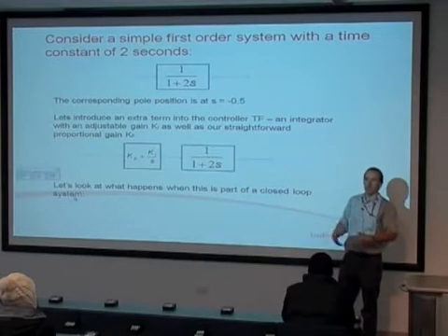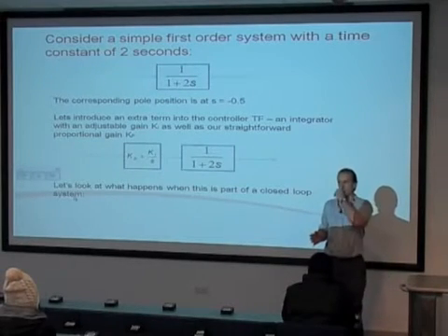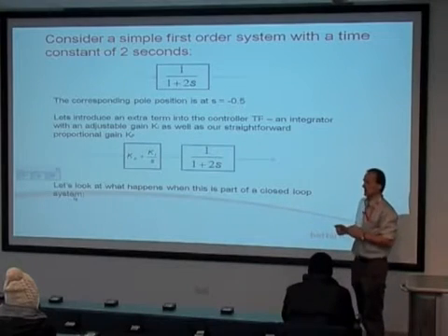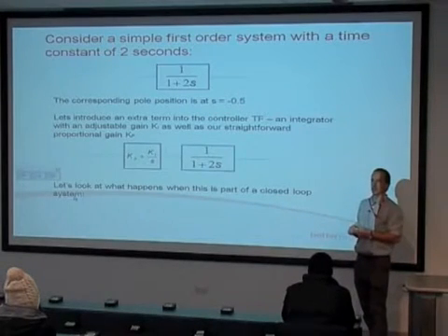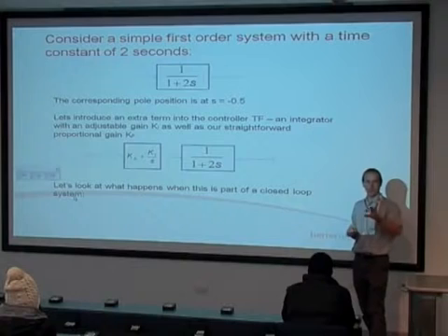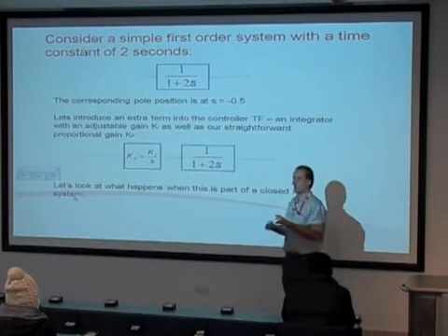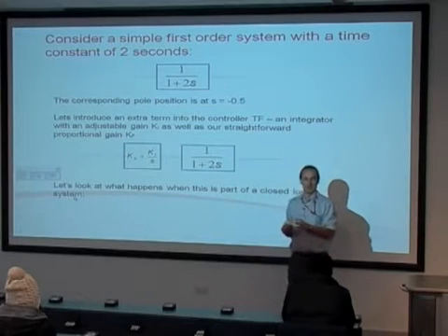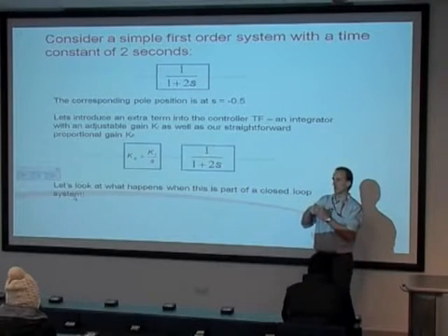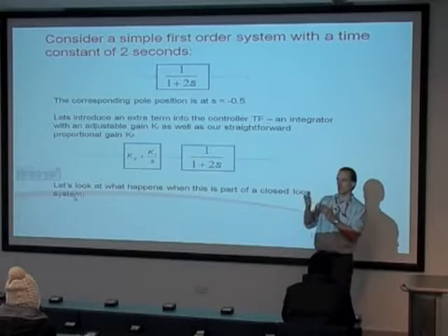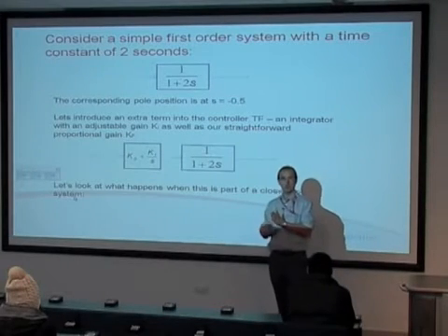And that's going to give a particular sort of dynamic behavior. If I introduce a gain into that system, then effectively what it's doing is changing the size of that error signal. If I put in a gain of about 10, then if I'm going a little bit too slow, I get an error signal, let's say 1 mile per hour too slow.